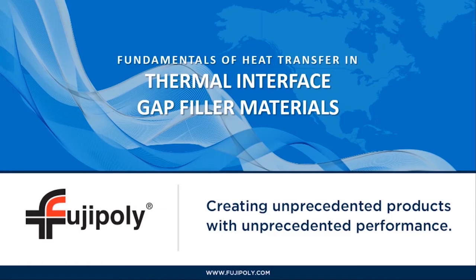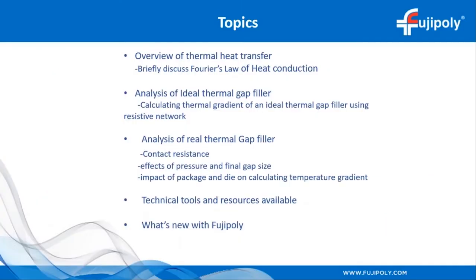A couple of the topics that we're going to be discussing today: we're going to focus primarily on our thermal gap fillers. We also make other products such as gels, greases, and thin films. For the most part, the principles discussed will apply to those materials as well if you make changes to some of the assumptions. The topics are going to be Fourier's law of heat conduction, and selection of an ideal thermal gap filler based on calculated temperature gradients.